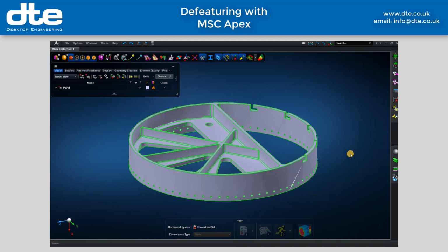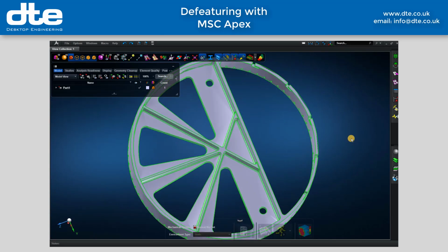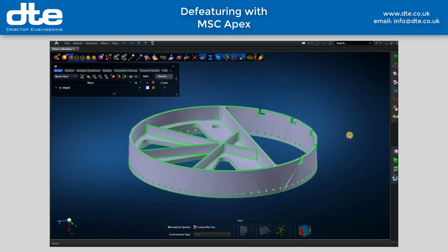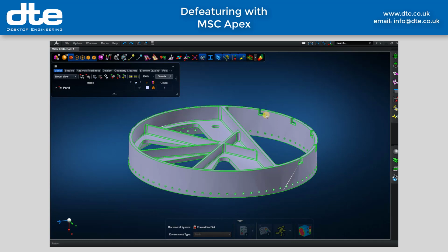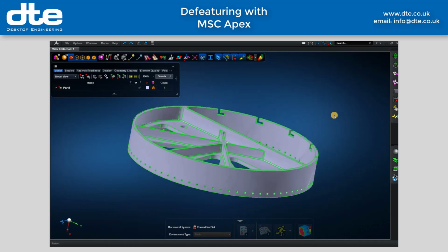Hello, in this short video I'd like to give you an introduction to the model defeaturing capabilities in MSC Apex. Apex can read in CAD geometry from most of the native CAD vendors, as well as neutral formats such as STEP, IGES and Parasolid. Typically when you read in CAD geometry to produce a finite element model, you find a number of features that you don't actually want to include. Things like very small holes, very small fillet radii, potentially even irregular shaped notches in the part.